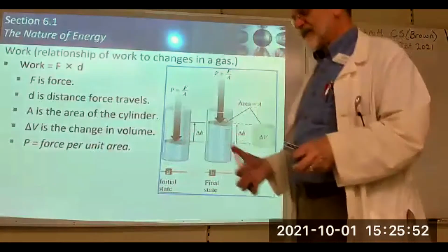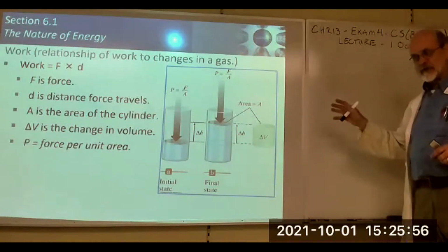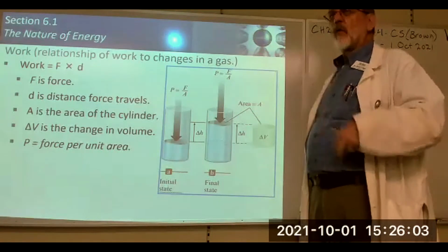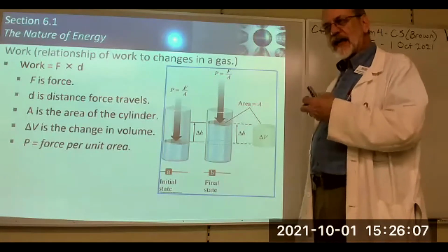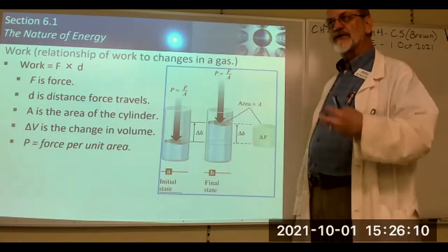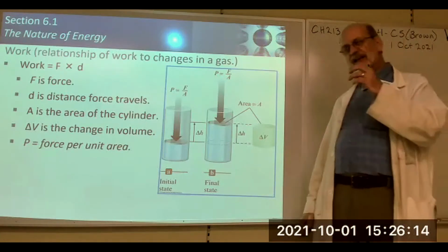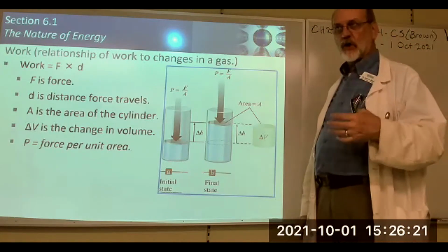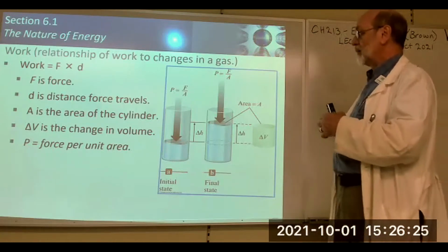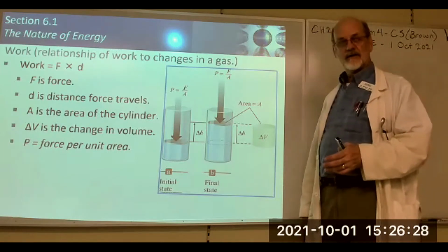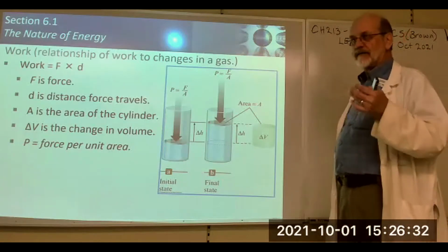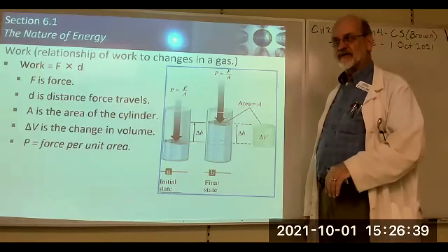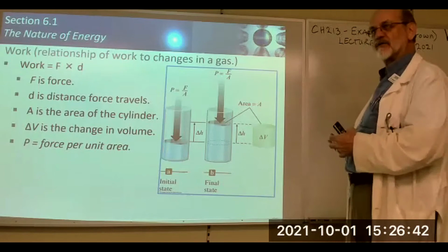All right. This discussion on these next two or three slides has to do with one way that leads us to a better understanding of how we can do work on a system, or how a system can do work on its surroundings. Because it has to be in terms of force times distance, technically speaking, to satisfy the conditions for work. So one way to do that is to define our system as a gas, because unlike liquids and solids, gases are compressible. I mean, we can get a distance moved with a gas, but we can't with a solid or a liquid. So let's stick to gases for the time being.